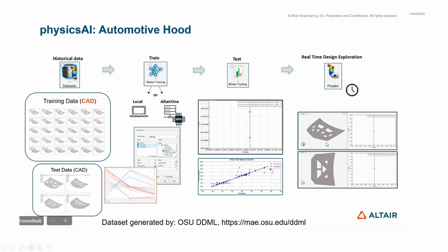There it will give you the metric score, which is nothing but a prediction score, showing how much percentage it matches your existing data. The more data, the more accurate results you are going to get, so 85%, 95% will show on the display. It is very simple in nature and does not need any coding. You directly drop the result files into the datasets, train the model, and then test the model to check whether physics AI is predicting properly. Finally you drag a CAD model into the physics AI window and predict the physics.